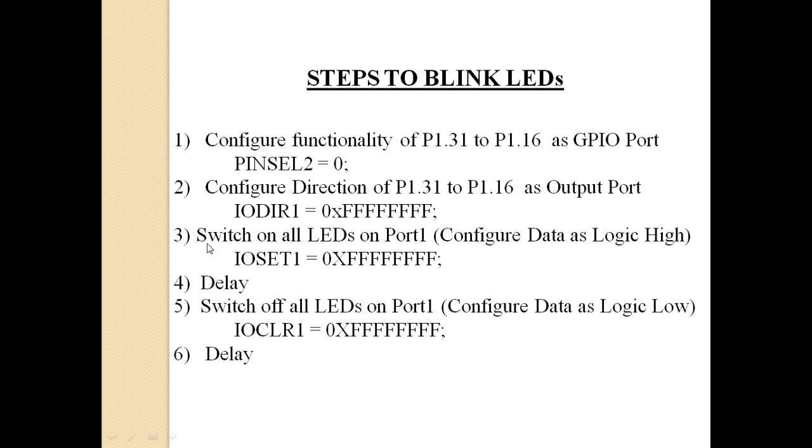Out of that, steps 3, 4, 5 and 6 should be inside an infinite loop. These 4 statements should be inside an infinite loop, because this program is for blinking an LED infinitely. That means you need to switch on the LED, give some delay, switch off the LED, again give some delay. So the LED is on and off. Again you need to do this process. So these 4 steps should be in an infinite loop. Then only you will be getting the blinking effect.